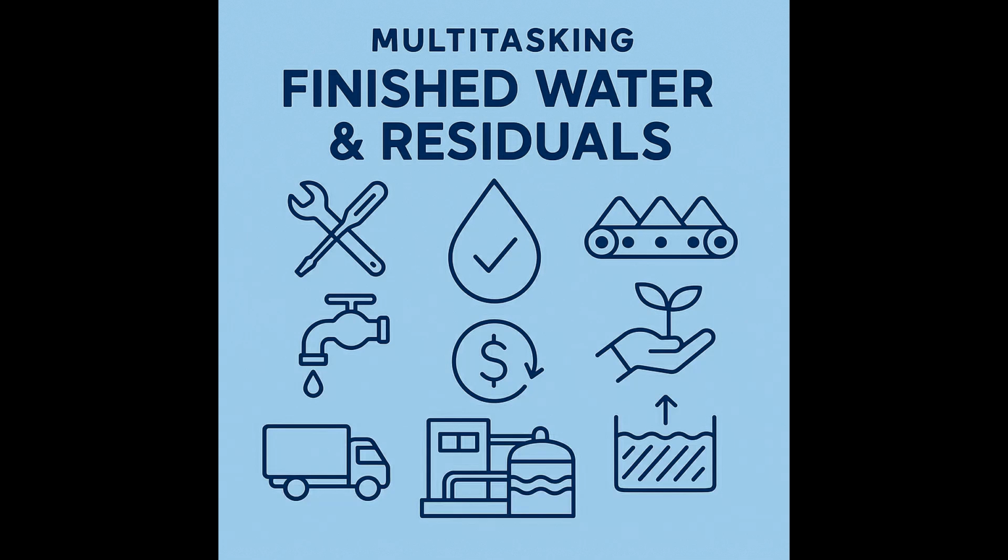which impacts hauling costs. So it really sounds like when a facility manager says residuals are 20% of my O&M budget, what they're really saying is, all this sludge handling, the thickening, the dewatering, the polymer, the hauling, that's the hidden, expensive half of my operation. It's not the glamorous part maybe, but it's where efficiency can make or break the budget. In perfect summary, it's absolutely critical.